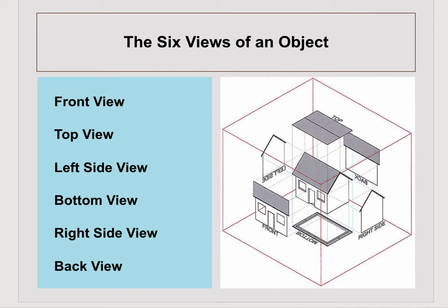All right, so the 6 views in this case, translated would be, so top could be the roof plan, which is literally looking straight down from space. The top can also be the floor plan. And the floor plan is a section through the building that is cut horizontally 4 feet off the ground.